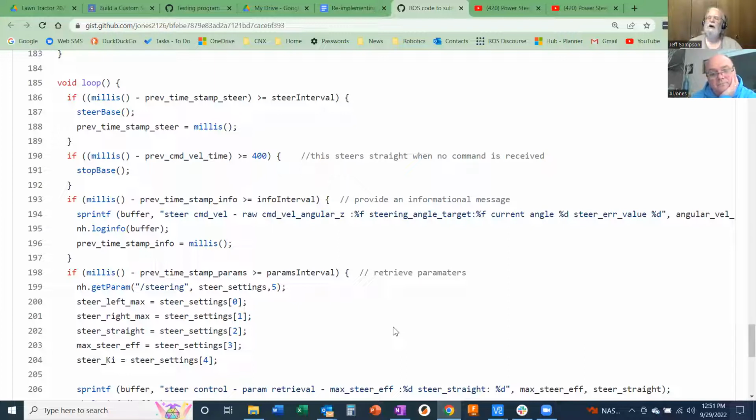Now on a Teensy or the ESP32, they may have a USB port coming directly out of the processor chip. So you might not have any actual UART serial data in between your print statement and your IDE on your Arduino, in which case it may work just fine. You might be able to put out anything you want and everything will be fast enough that it doesn't care. But if there is a physical serial port in between there, that may cause problems for you.